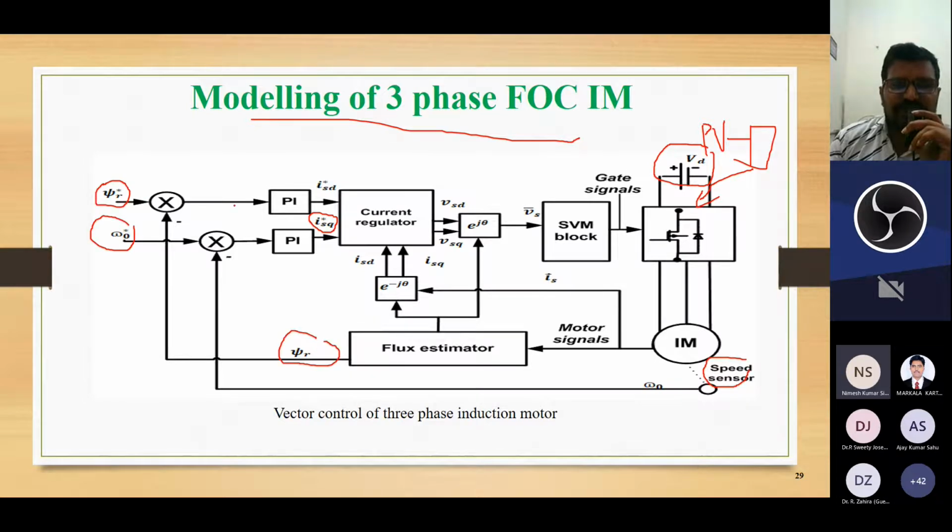So which is compared with the reference flux, and then we achieve the direct stator current of reference direct current. Once we transform these entire signals into voltage values, we can achieve the reference Vs. So this reference Vs is nothing but the reference Vr. What we have discussed previously, Vr in SVPWM. So this Vs is nothing but Vr at an angle of theta.